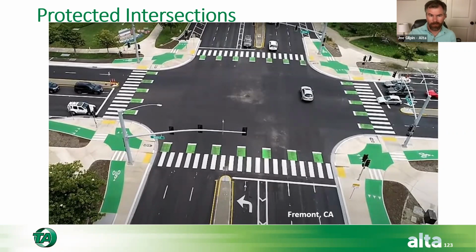It's really an architectural treatment when you're in the corner, but once you get to the intersection, you do need to use the green. And so there's red, there's Minneapolis and other communities have used a black additive that they call black ice. It's a pigment that colors the concrete a dark color, and it looks kind of like asphalt, but it's not. It's still concrete. So those are nice treatments that you can add to it.